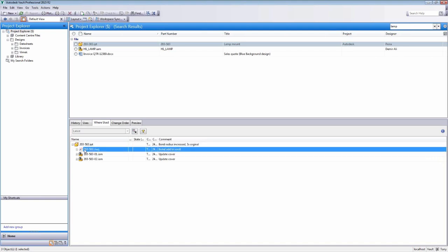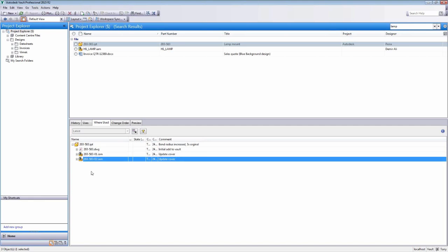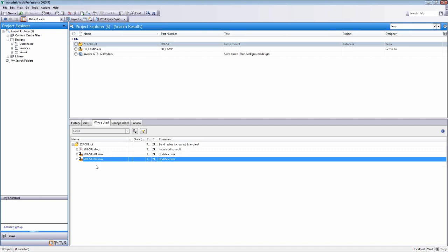So it's currently used in a drawing of the component itself, but it's also used in these assemblies. So if I make a change to this, will that assembly and that assembly work? Will it affect them appropriately? And in this case, I don't actually want to do that. I want to create a third version because I want to leave those ones as they are. I don't want those two versions to be updated with my changes. So it starts giving me the ability to understand my design changes before I've even committed to modeling anything up.